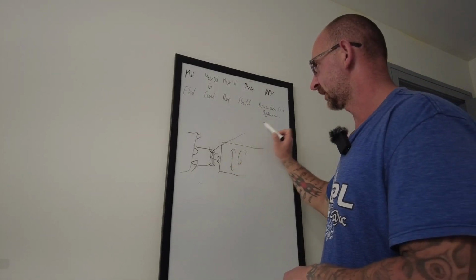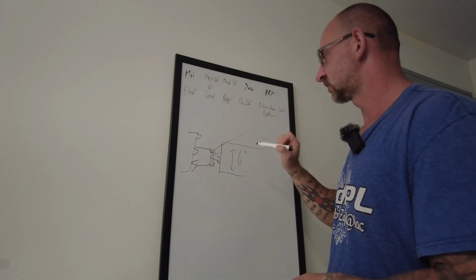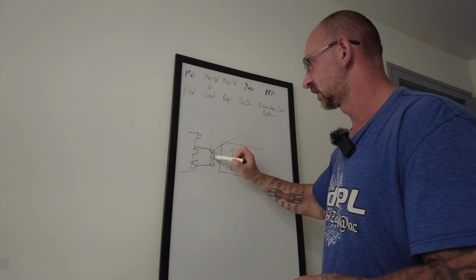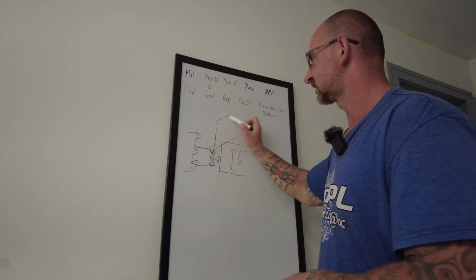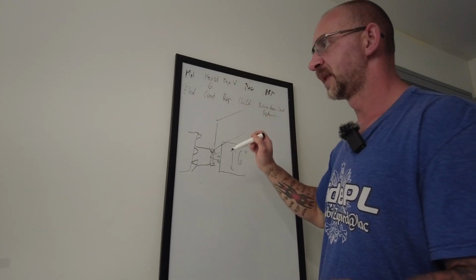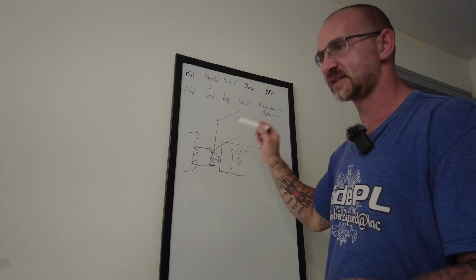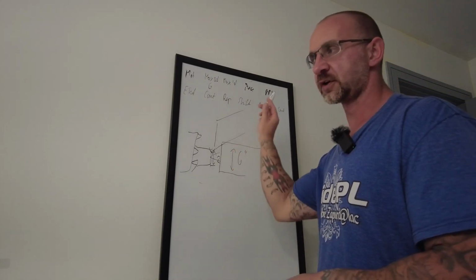Because it's going to go head home straight. But if your max OD is set to 6 inches, it will cut the chamfer, come up to 6 inches, and then go home. So technically, that max OD is telling the machine that you have a 6-inch part, so go to 6 inches or above before heading home.